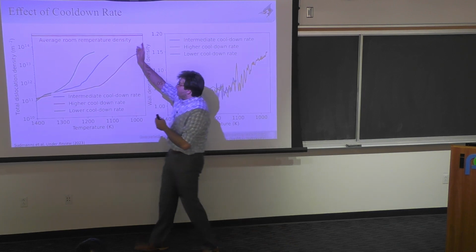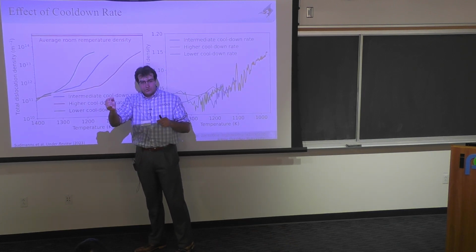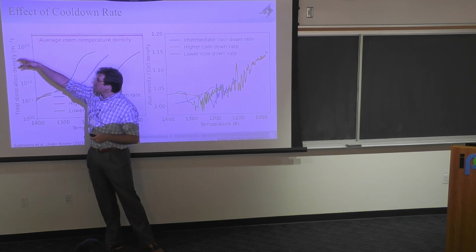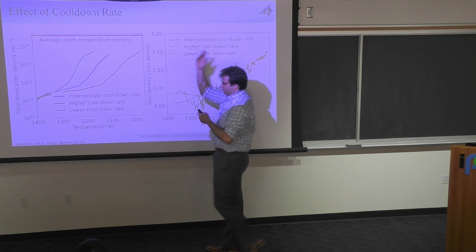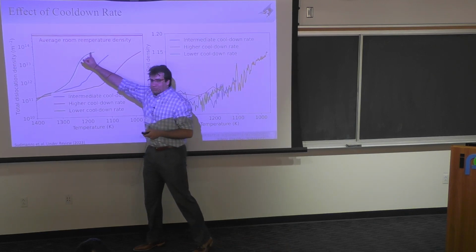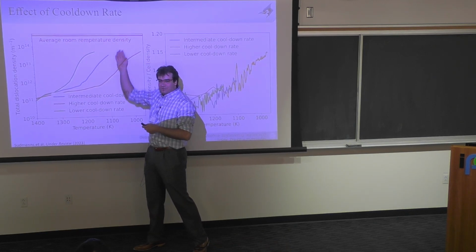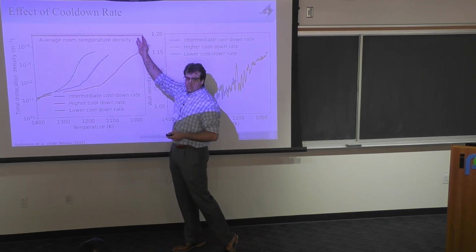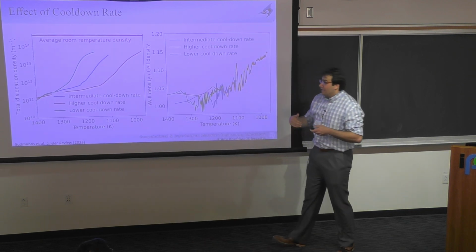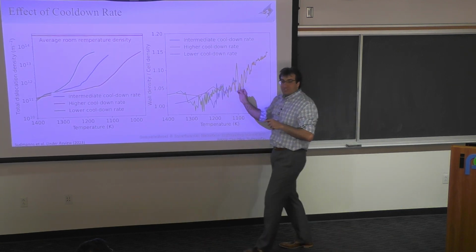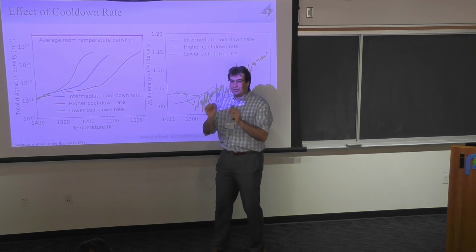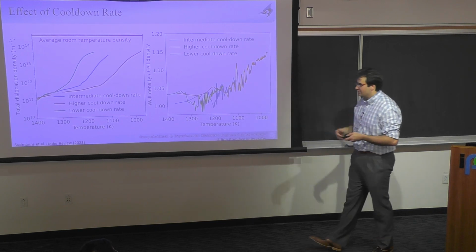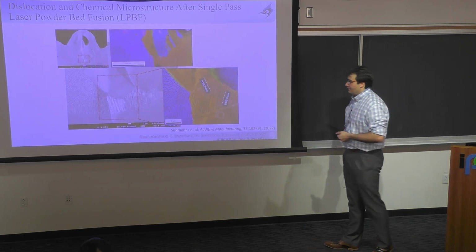The other intriguing thing here is, if you look at room temperature when they do these TEM foils, they extract the dislocation density. That dislocation density is up here. So it's on the order of 10 to the 15, 10 to the 14 plus. We basically reached 10 to the 14, but you can see that all of them are trying to transition, and eventually if I'm able to cool this down further, we think that ultimately we should reach that dislocation density, but we're lower. And if you compare the TEM images versus our dislocation dynamics TEM images, you'll notice that our densities are actually lower than those in the experiments. And we know why. It's just I haven't cooled it down all the way down to room temperature yet.